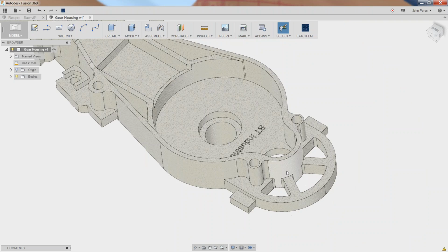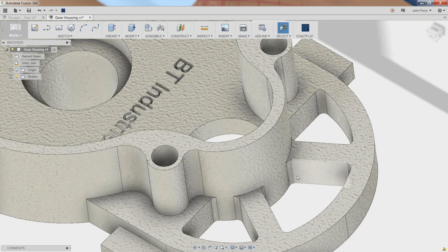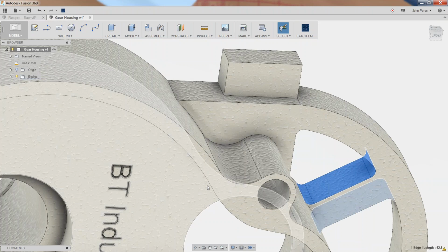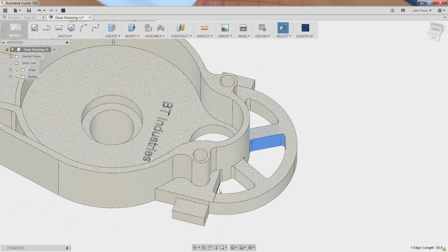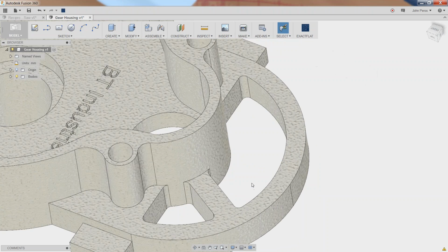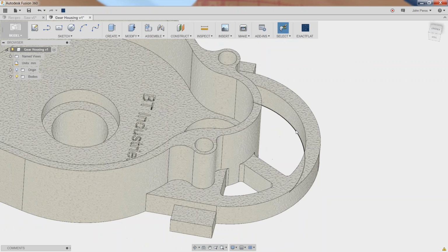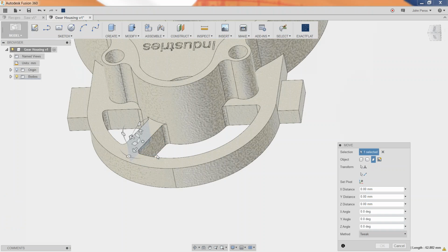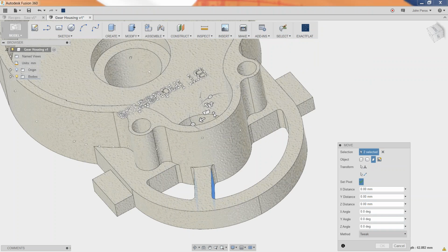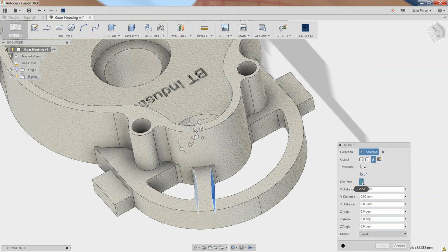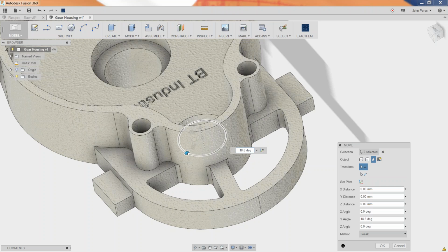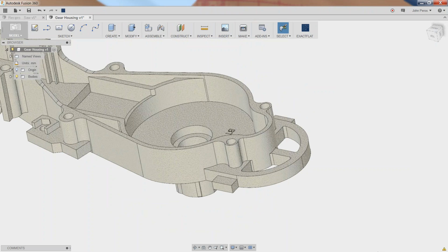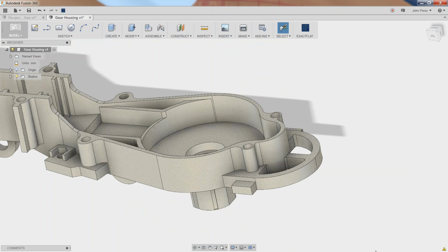Or you look at the back half here, we've got 2 support brackets. Well, maybe in our example, that's too much and that's going to drive up the manufacturing costs. We only need 1 of them. Well, I can select the faces associated with one of those supports and hit delete, and Fusion will actually patch that geometry out for me. But more than that, I can now move the existing one into the center so that this thing looks symmetric. It doesn't look funky with it all off-center like that. So I can grab this and just rotate it 30 degrees into the center of the model, and I've done all that with 0 feature history on an imported model.